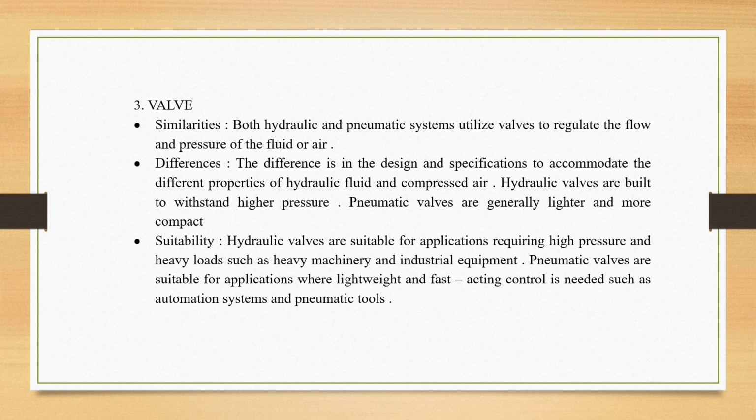Pneumatic valves are generally lighter and more compact. Hydraulic valves are suitable for applications requiring high pressure and heavy load, such as heavy machinery and industrial equipment. Pneumatic valves are suitable for applications where lightweight and fast-acting control is needed, for example automation systems or pneumatic tools.